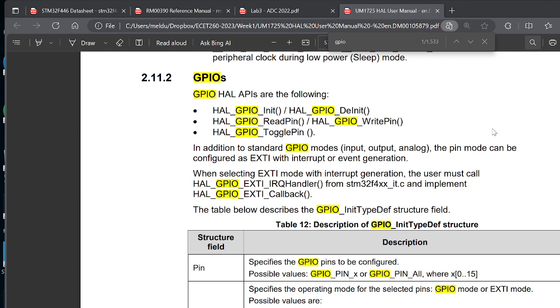By default, when it initialized everything, the button B1 is going to be set up on an interrupt. You could use an interrupt. We haven't really talked about interrupts, so I just expected you to take B1 and set it to an input so you can have HAL GPIO read to go in and read it. We are going to deal with interrupts and all sorts of other things coming up, but I don't want to get ahead of ourselves with this.